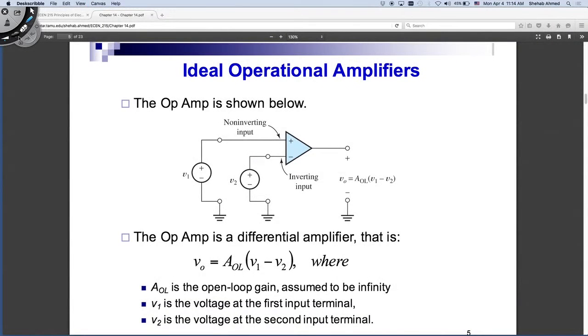Remember I said it's a more complicated sort of transistor circuit. With transistor circuits, the main thing is the external power supply, right? So I would typically also have an external power supply. Sometimes it's positive and zero, and that is called a single rail op-amp, or sometimes it is positive and negative. Right? This would be a positive, this would be a negative. I have a battery that's flipped, and this is called a dual rail power supply, dual rail op-amp, and it's exactly like the transistor circuit.